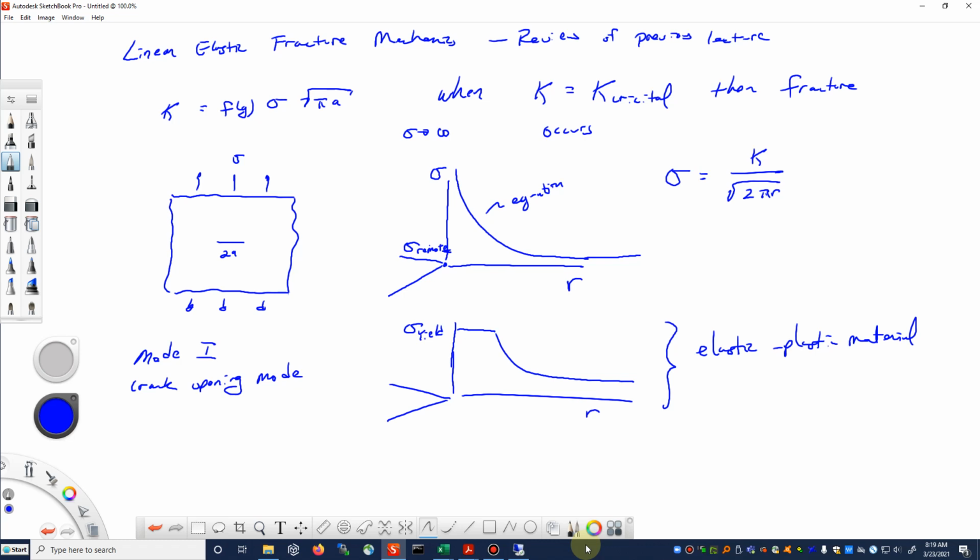Now, does it look exactly like this picture that I've sketched? Well, probably not. Some materials experience hardening, so the stresses may still be yielding, but the stresses may increase a little bit over here. It may kind of flatten out and come down and join this curve. But what I've drawn is an idealization for what's called an elastic perfectly plastic material. If we looked at its stress strain curve, it would come up, hit some value of its yield stress and basically move over flat. Oops. Let's say elastic perfectly plastic.